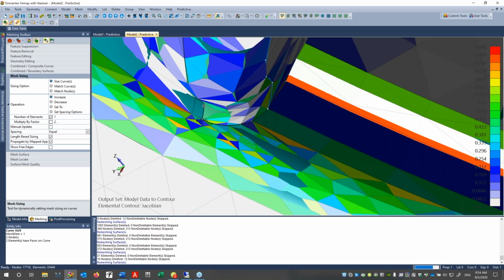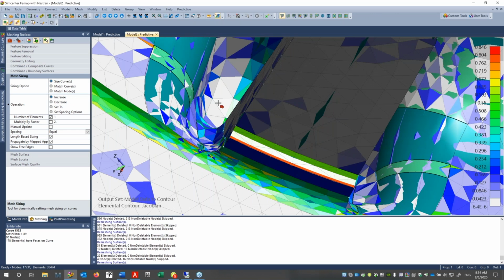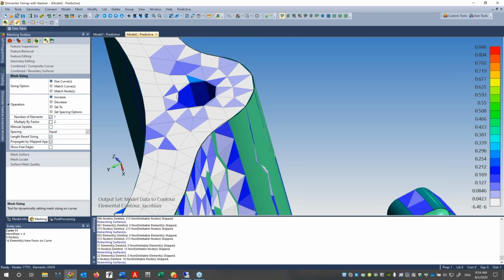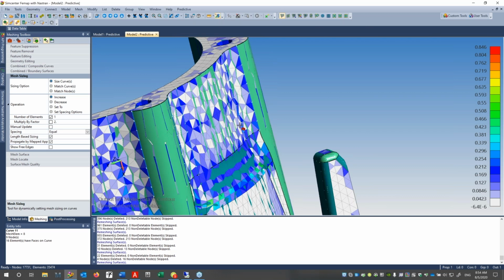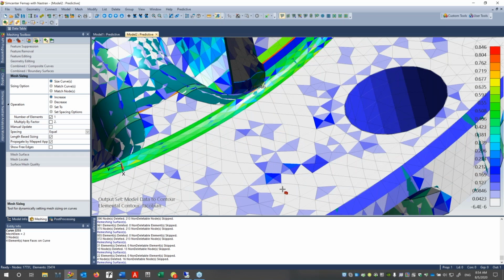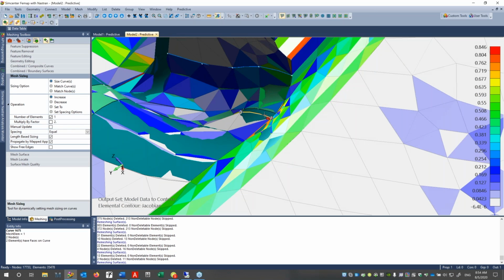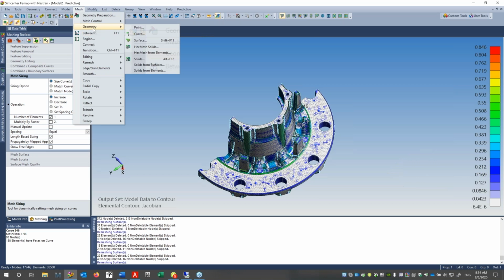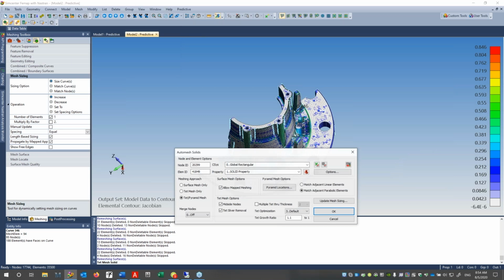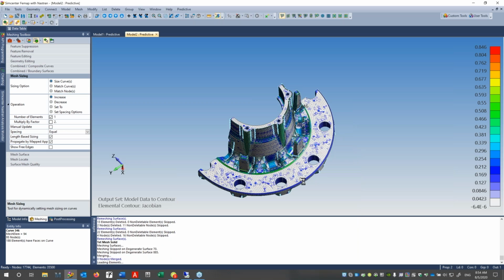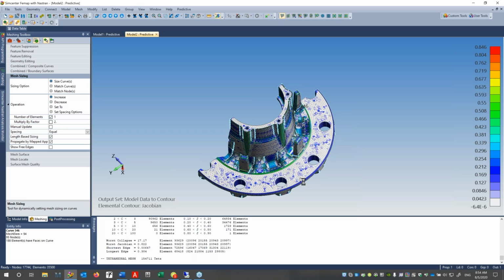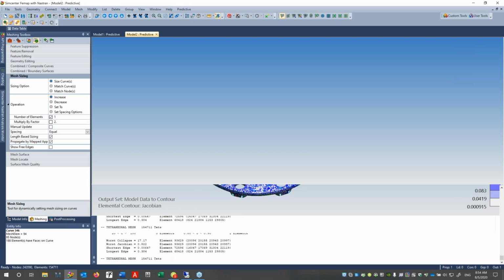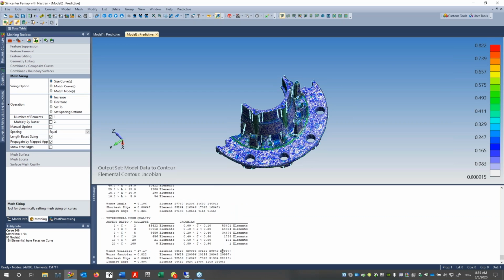Plus, this is quite fun. This is hacking on meshes. It is addicting, and I hope I'm not making you guys dizzy with the mouse and the movement going around and around. But so now I'm down to 846, and now you go mesh, geometry, solids, and it takes what you got, meshes it, and we're 0.822. And then you look at the statistics and you go, yeah, there we go. We only have one element, about 0.8.